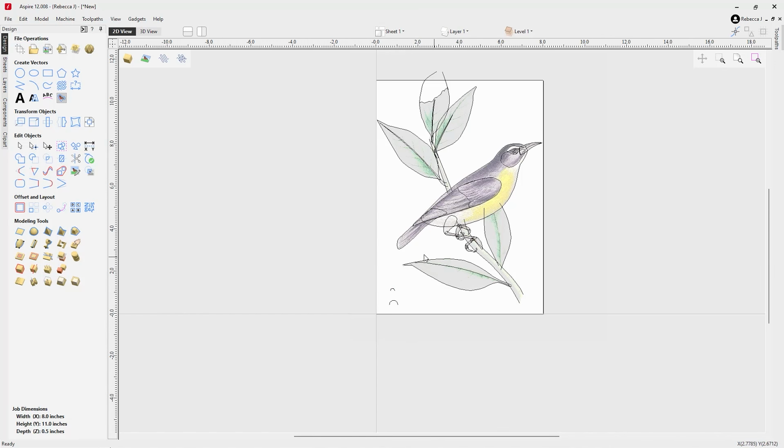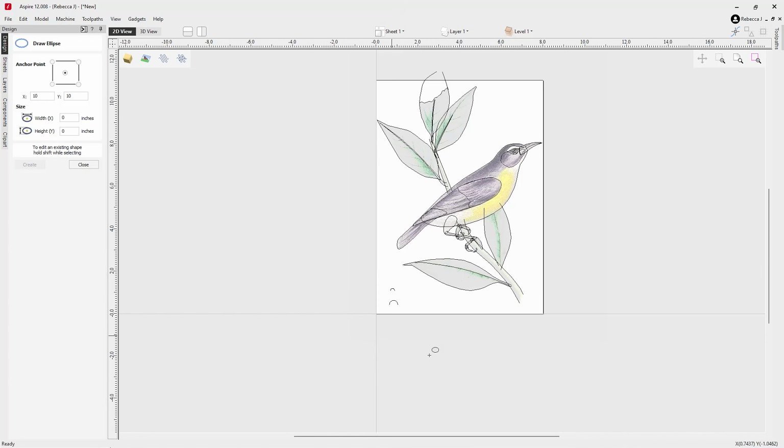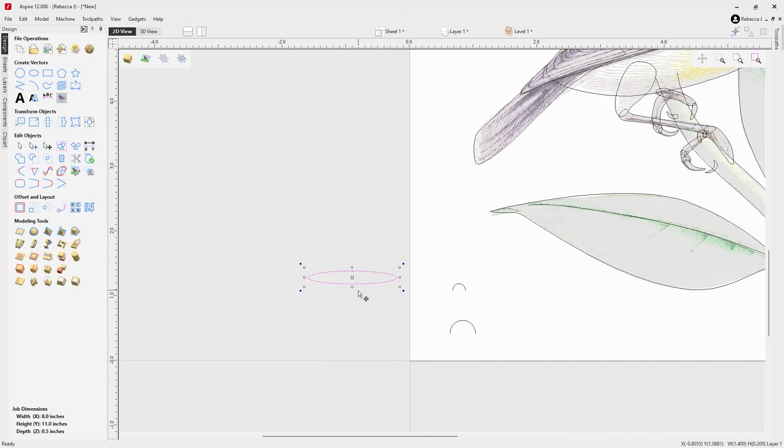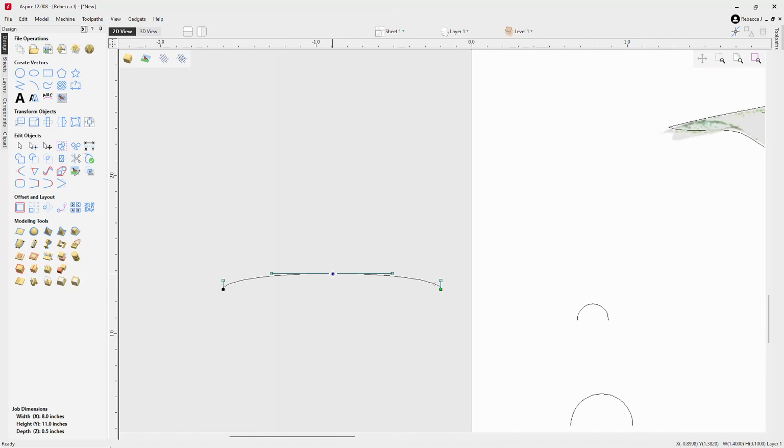In terms of the leaves, my favourite trick for the leaves is to draw an ellipse. Okay, we're just going to roughly draw an ellipse out, something like this, and then we're just going to right click to come out into node edit mode. We're going to delete those bottom spans here, and then I'm going to change this into a straight point, so I uncheck the smooth point.